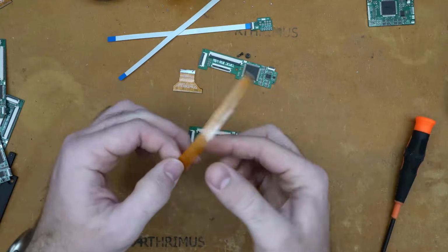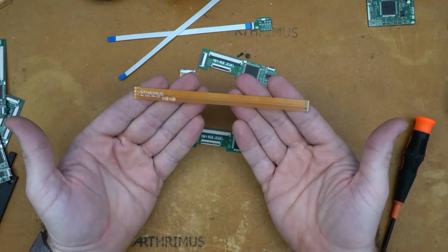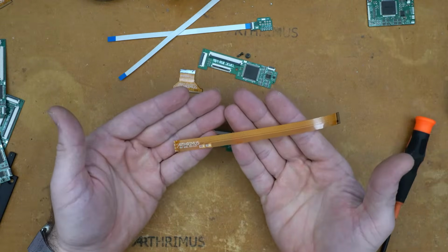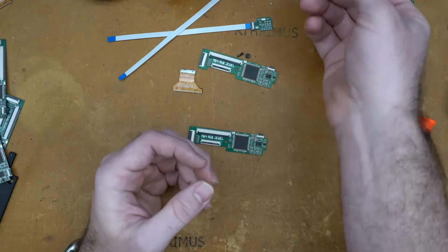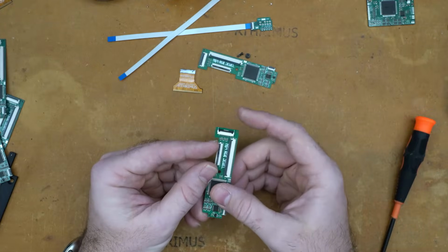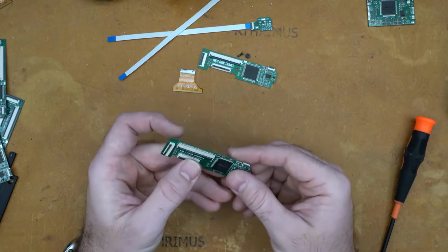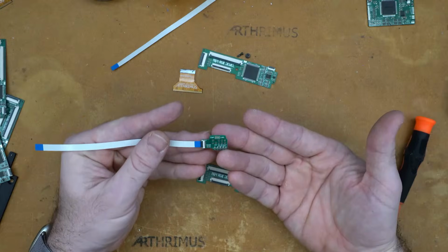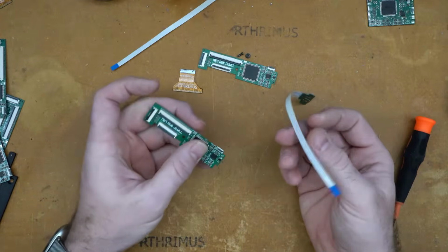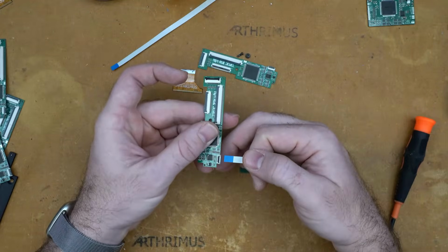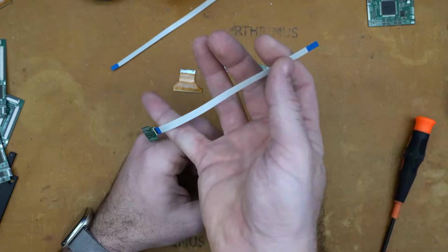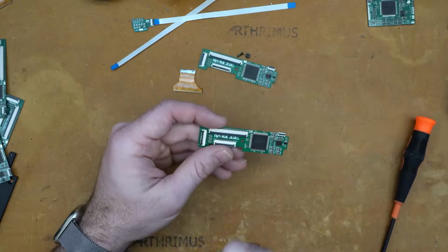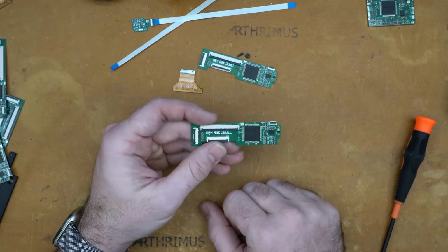And I have a flex that I designed for standalone installation. So this flex you would just solder into the N64 just like you would a Retro GEM flex or something like that. And then it just connects to this connector at the back of the board. And then you have your AV out board, which connects to the AV out. And then that connects to the board right here. So basically everything is flex cables now, so you don't have to solder the individual wires. You just solder the flex cables into place and then you're done.